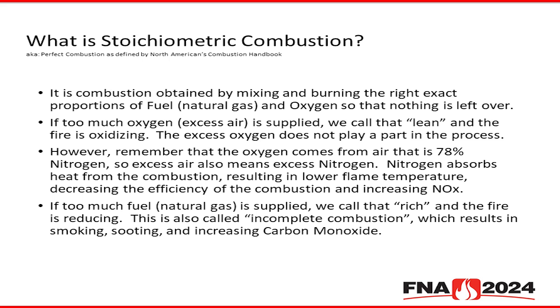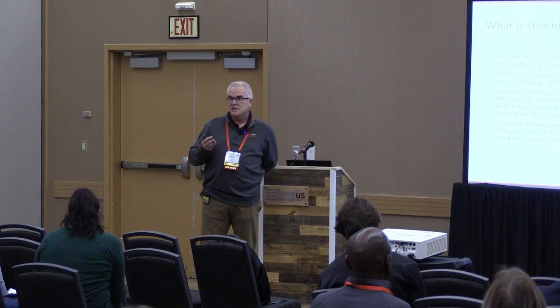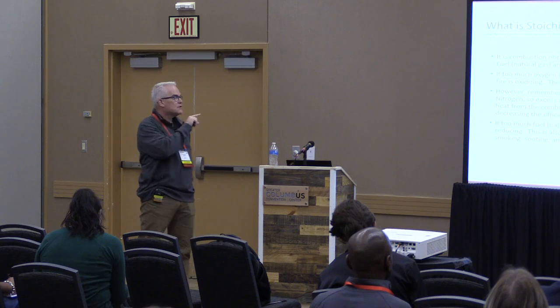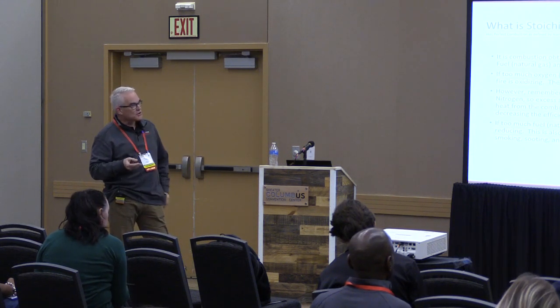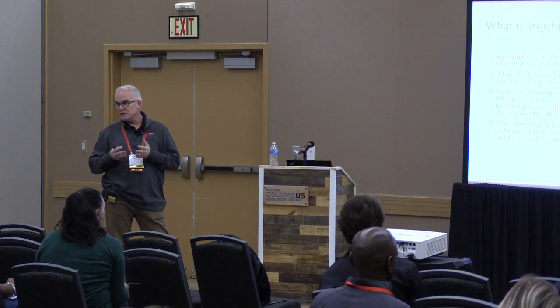If you have too much fuel, again, natural gas, that's referred to as rich. So again, these are super technical terms that we use, rich and lean, but they do represent something. Fire is reducing. It's also called incomplete combustion, which results in smoking, sooting. Sometimes you even see it's almost like it's snowing carbon around your burners.